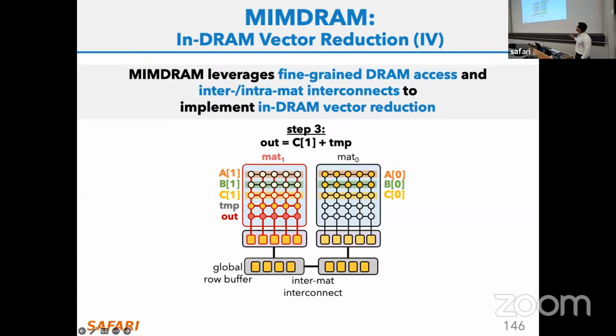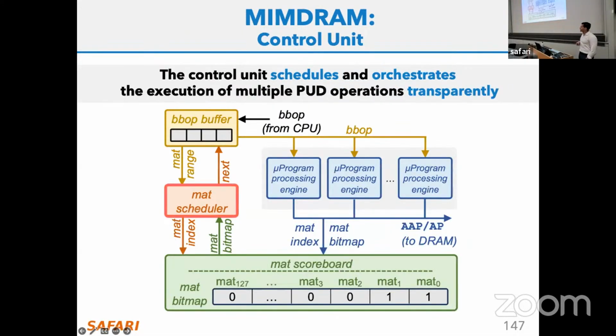So I didn't draw the adder tree here, but hopefully when I say adder tree, you understand more or less that if you spread the data, you do one adder with another adder in one level, and then another node that connects the inputs of the two previous ones. And then you keep repeating that in that tree structure. I should have drawn this, I just realized that now. But anyway, hopefully it's more or less clear.